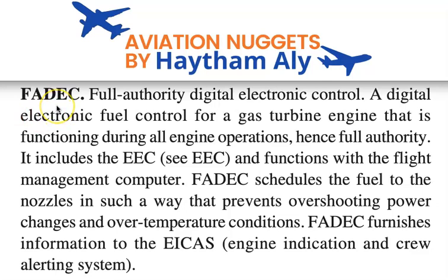We always care about the EGT because the exhaust gas temperature directly influences the turbine. The turbine is the major component of the engine. The turbine is made of a specific material, and each material has a limit value. After that, a problem may happen to the turbine and the engine will stop due to the high EGT.